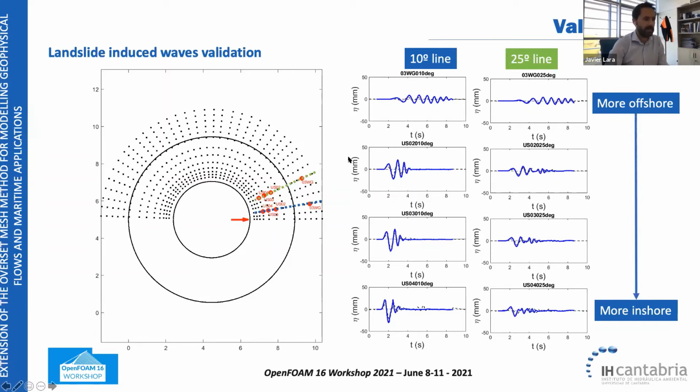You will realize how good the performance of the model is, which is able to capture this transient effect with very good accuracy, even capturing the amplitude of the waves and also the phase of the waves. So the period is also very well captured, and you can see how it is able to simulate also how the waves dissipate while they are moving to offshore locations, due to the fact that this element is radiating energy to other parts of the numerical domain.